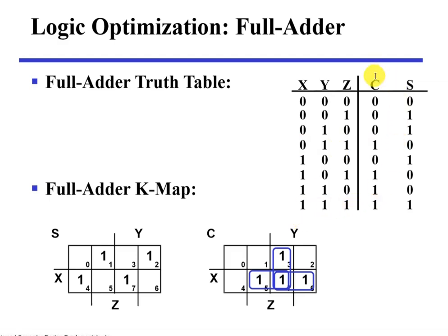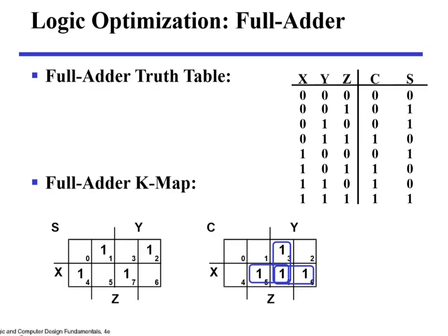Right? We can form the map, the K map, okay, for 2 outputs to represent the full adder in terms of the optimized Boolean expression, right? So this will be the example of the K map for 3 variable K map, where we put the minterm locations, right, in the K map and then form the grouping. Now we can form the grouping of the minterms.